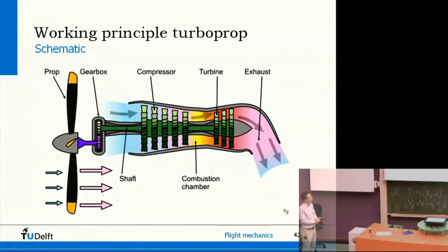and a turboprop is the type of propeller you see on most civil aviation aircraft. If you look on the right-hand side, the whole engine part is the same as the jet engine. There's only one difference. The turbine in the back is used to drive the compressor. You have this high-pressure gas in the combustion chamber which tries to expand. It's very warm and goes through the turbine, but in a turboprop you have a somewhat larger turbine.